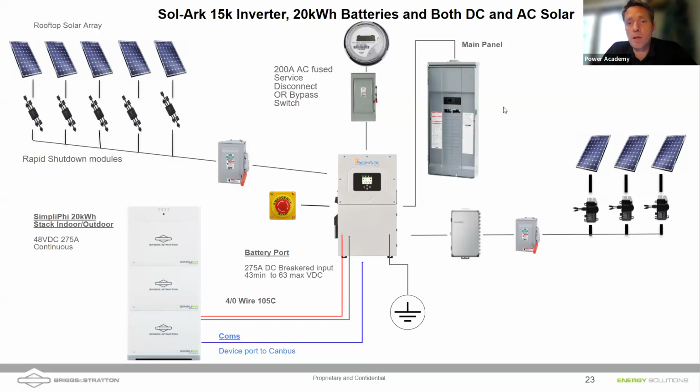What that does is it makes everything safe, right? So if there is a fire, if there is an emergency, that means that the panels are all shut off at the panel level, which is required by that rapid shutdown requirement.